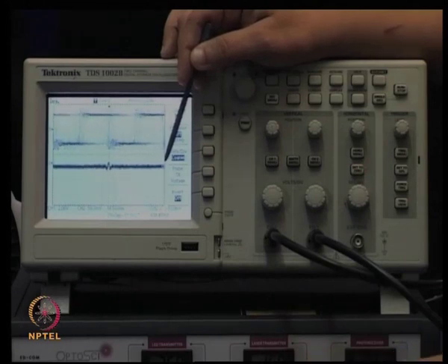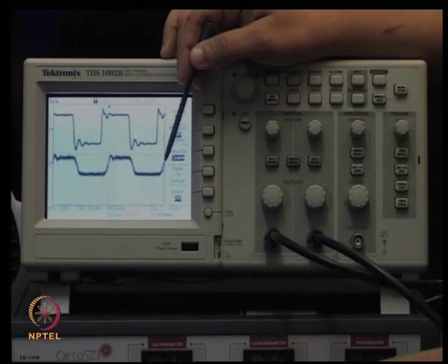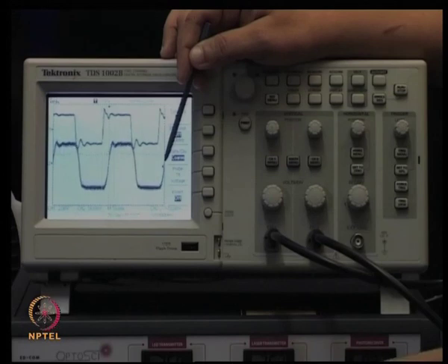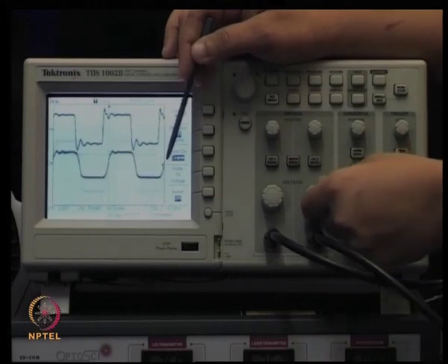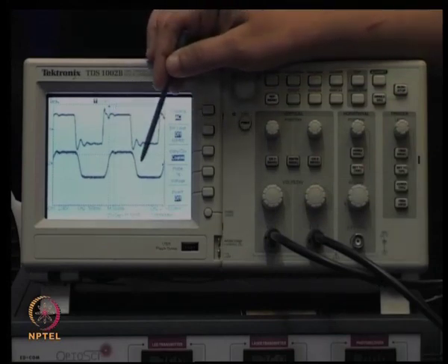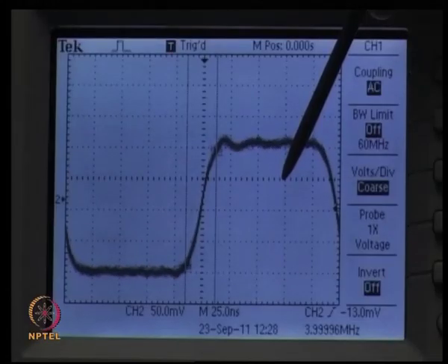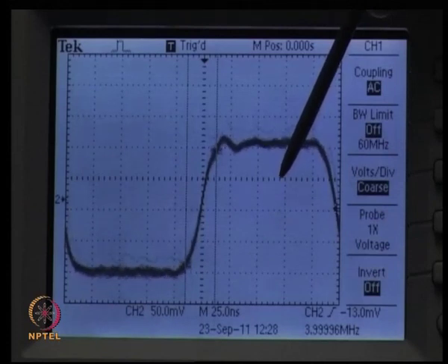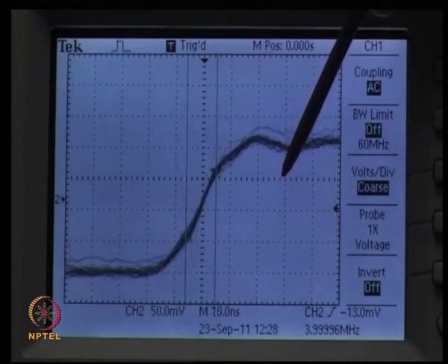So as we increase the power of laser transmitter, after a certain value, lasing starts and we get a sharp increase. Below the lasing current, received signal was very less. Here also we can see an increase in the rise time. We will now measure the rise time of the received signal.